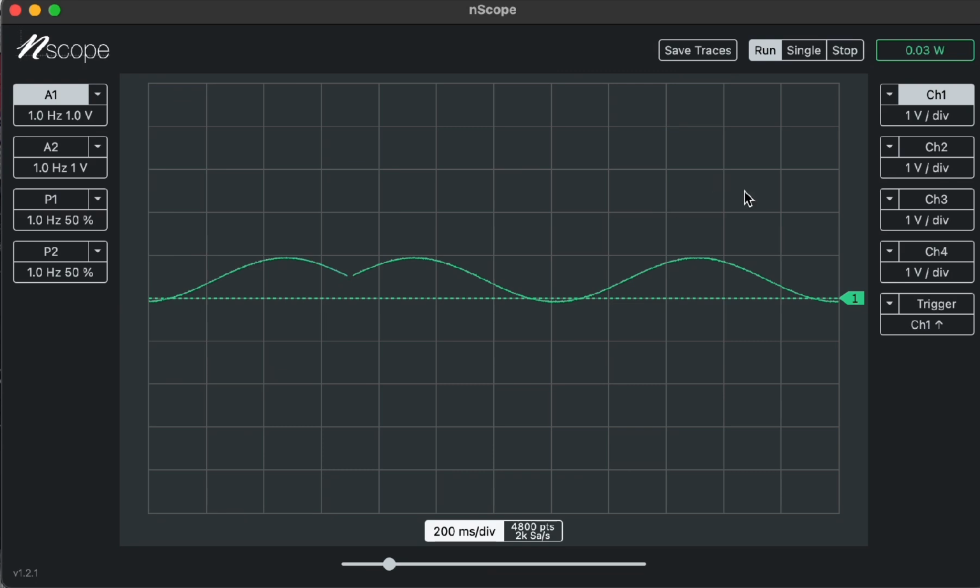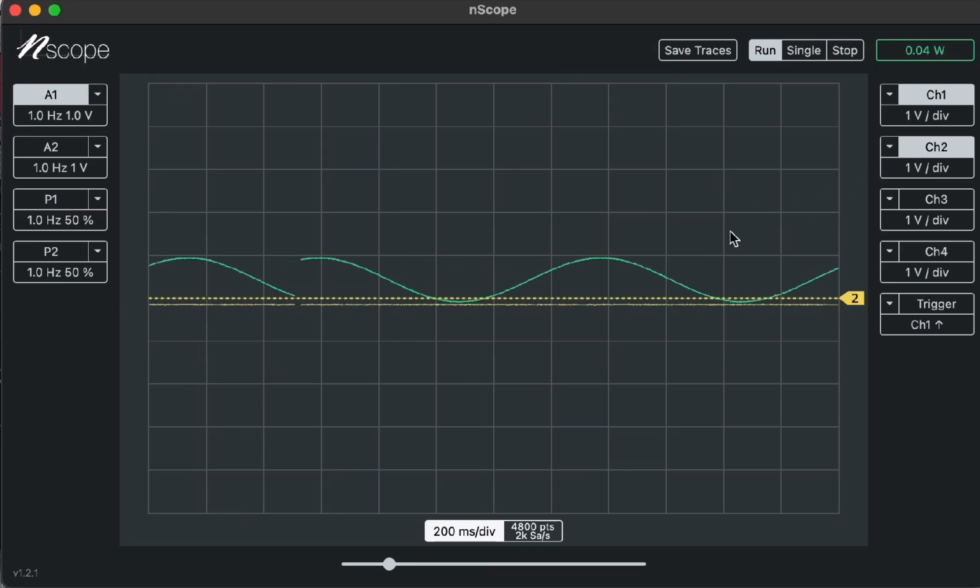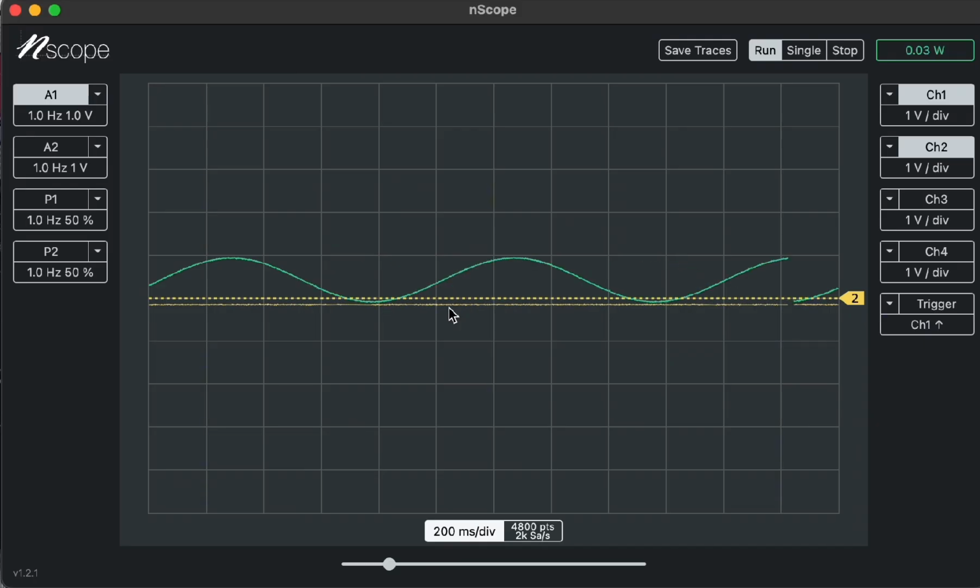So I'll click on the channel 2 button to turn that oscilloscope input on. And right now we see that it's always 0. So the LED never turns on. We've verified that. It turns out that LEDs have a minimum voltage before they'll turn on. That means my signal generator has to apply a bigger voltage to turn on the LED.